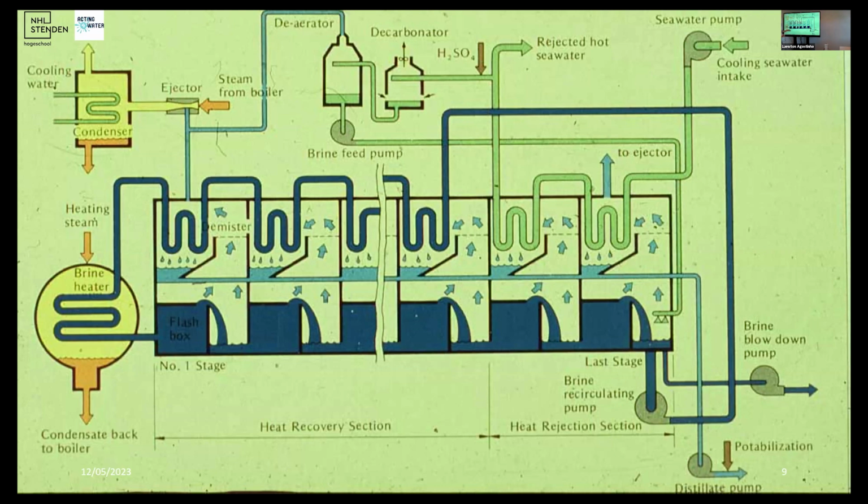So in this case, I'm just multiplying the stage here. As you can see, at the last point you will always have a brine blowdown. You always have a brine left from the feed. Why? Because as we discussed last time, in desalination you don't want to move to very, very high concentrations in your brine. You want to keep it to a certain percentage to avoid high concentrations that would eventually cause saturation of the salt, which will cause deposition or scaling in your tube bundles, and it will stop the operation or even generate very costly maintenance actions.